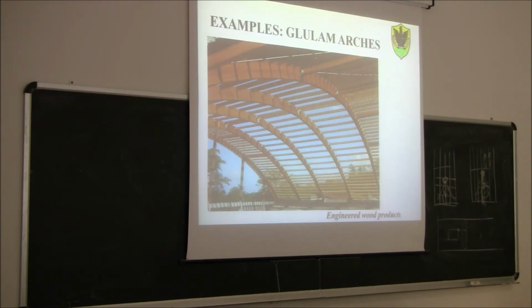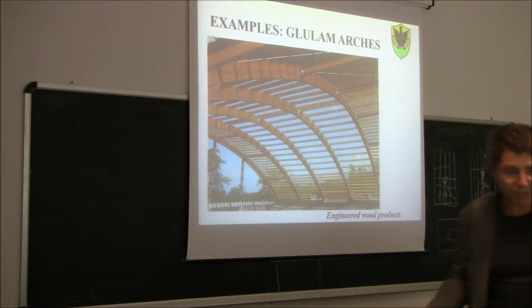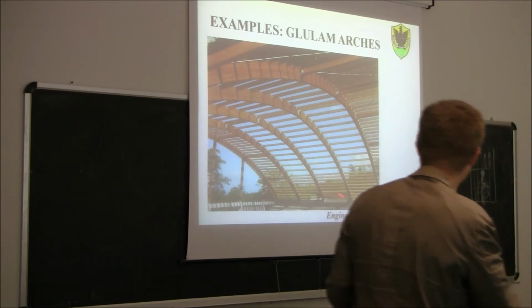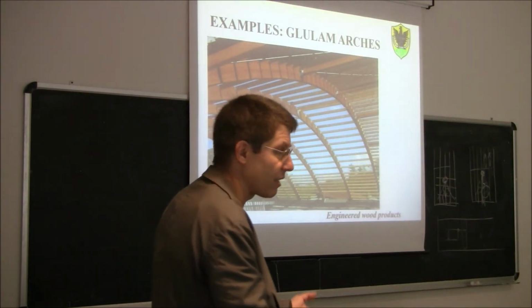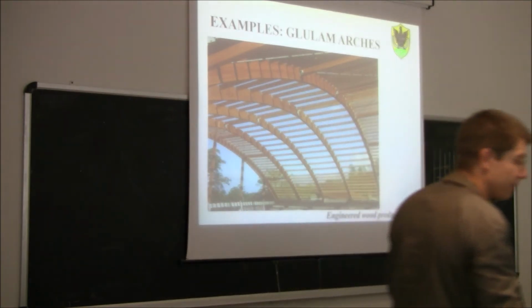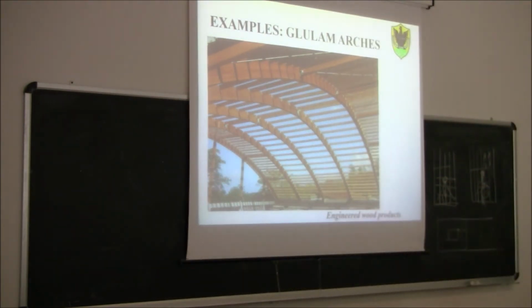We will talk more about bracing systems later on, because as you can imagine, unlike a reinforced concrete structure, which some of you studied 1-2 years ago, where all the joints are rigid, here the system very often may be unstable, because we very often use pin connections. So the bracing system is really needed in order to carry the horizontal loads.